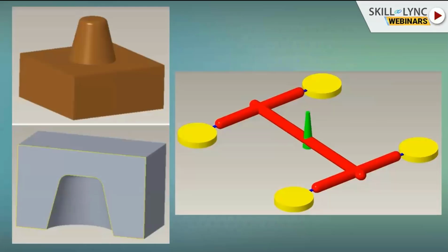In this picture, you can see that what is highlighted in red is known as a runner. The picture I'm showing is a multi-cavity mold. Multi-cavity means that if in a mold there are a number of components, like 2, 3, or 4 components being produced, we call them cavities. In this picture, you can see that it is a 4 cavity mold. Here the red one highlighted is the runner.